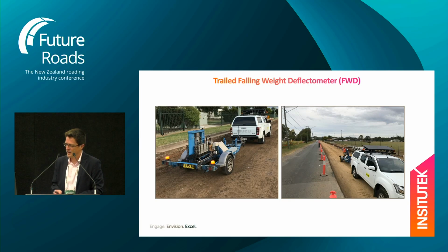So one other way that you may be familiar with, FWD. Who's familiar with FWD? Lots of hands go up. Okay, so FWD is great, but it's about having access to that capability. So availability of having access to a tool like this, and it's typically used for stiffer pavements, so it may be used on base layers. You can use it on subgrade, for example, but typically it's used on base layers or on top of the asphalt as well, or on top of chip seal.